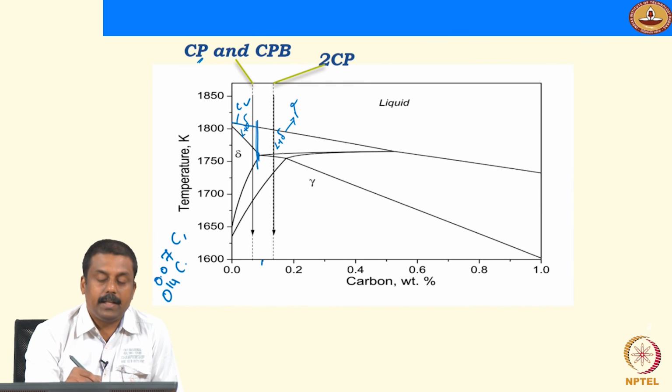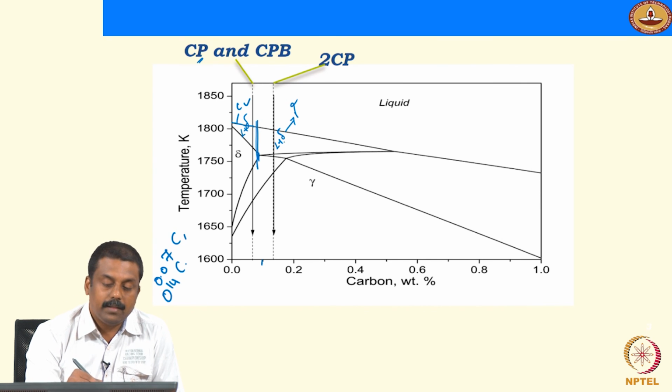Whereas if you have a peritectic reaction, the liquid solidifies into delta ferrite first, and then subsequently this mixture of liquid and delta ferrite will transform to austenite. Because of the higher solubility of carbon in austenite, the carbon segregation in the liquid can be decreased. So the solidification mode has a significant role in the carbon partitioning in the unsolidified liquid during solidification.